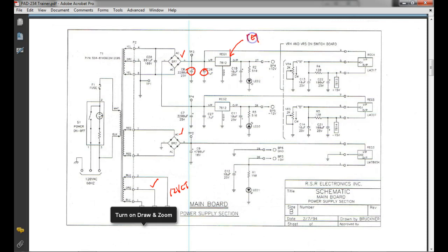And this is a fixed regulator. We'll talk about those. So this is an integrated circuit. So what do you need to regulate? You got to have a circuit. You got to have an unregulated in, a regulated out, and then you got to establish a common. So these are usually called 3-terminal regulators because of that reason.